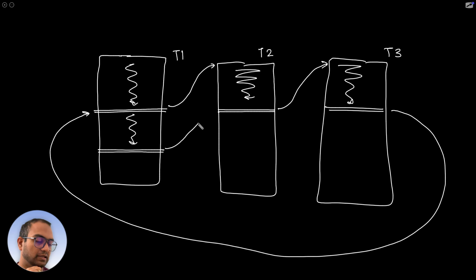So first things first, recall that wherever the program counter is pointing is the location from where the CPU is going to fetch the instructions. Which means that if we can somehow change the program counter value at exactly this point in T1 to the starting location of T2, then there is a chance that the CPU will execute T2. In fact, it will start to execute T2.